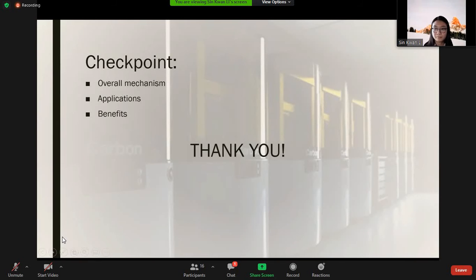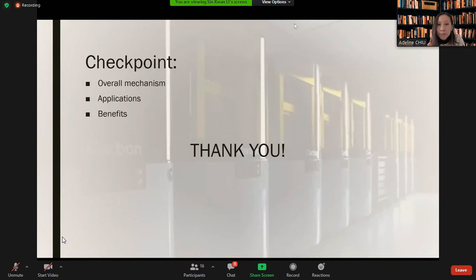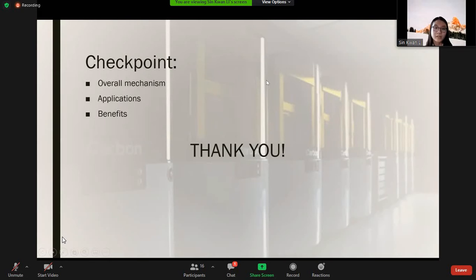Yeah, the question is about weaknesses or some sort of constraints. When compared with this one, this is printed by FDM, which is fused deposition modeling. So if we print out things with FDM, it's much cheaper, and it's good for designers to know how it looks for primary usages. But if you want to print out really detailed, refined products, of course, you may choose SLAs and what I mentioned, digital light synthesis, as it provides much more refined and detailed work.